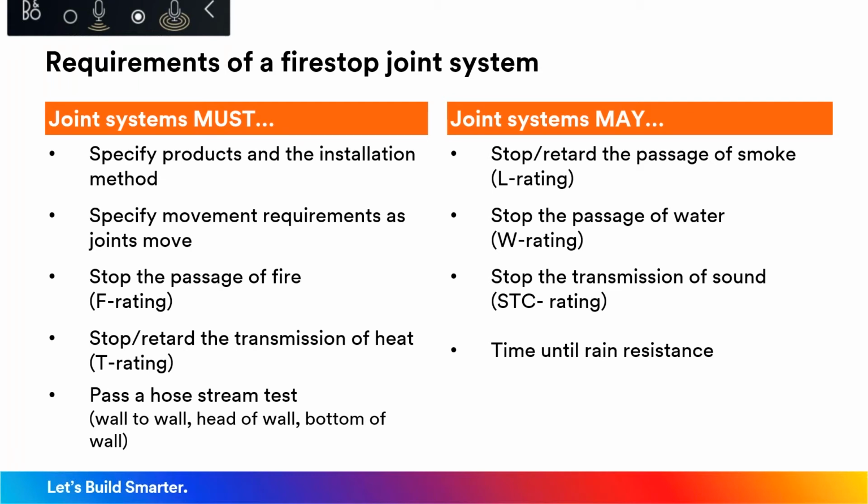It could be a slab edge, curtain wall type of joint, running horizontally, and it's going to have weather on it for a period of time. We need it to be watertight, rain resistant. It might need to have a specific amount of movement, depending on the design of the building, or if we're in a seismic region, that joint's going to need to move and move often. And so again, this is where it's not just the product, it's the system.